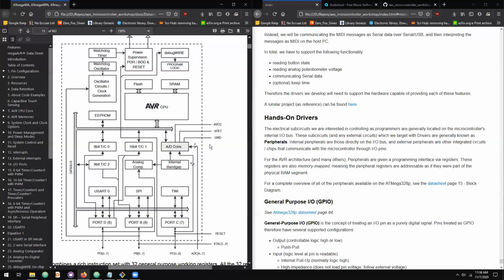So whenever I try to become familiar with a new chip, the block diagram is typically the first thing I try to find because it lists all of the functionality available. The next thing I try to find is a listing of all the specifications, like max clock frequency and then the electrical parameters, which are also found in the datasheet.